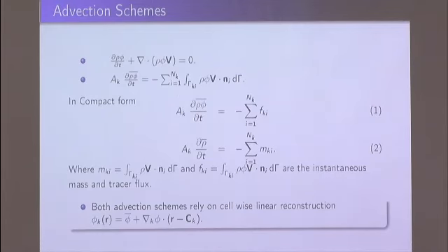So this is the flux form of the tracer continuity equation, and we can discretize this continuity equation for a control cell K. This is the area of that cell, and this is the average value of rho phi over that cell, and we have used Green's theorem, and this nk stands for the number of edges of that control volume. In our case, it could be either 5 or 6,